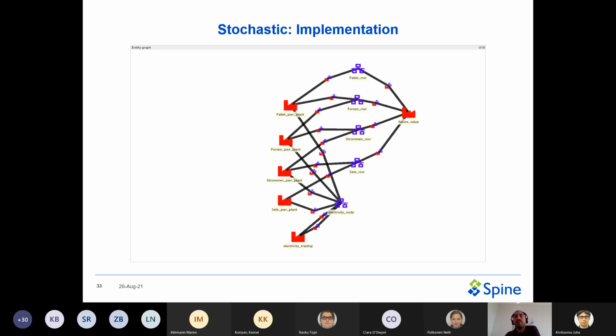So the effect that this will have is that in the last time step, the unit will take all the water that is in the reservoir at that point, and it has assigned a cost. So when the water flows into this unit, it does it at a cost, and that cost is a negative cost, a negative value of the future water. So this is kind of a clever way of modeling things in SpineOpt. Sometimes you need to come up with these interesting strategies of modeling.